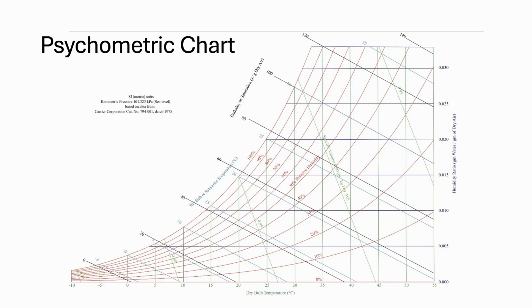So first of all, how much moisture can the air contain, and when is it that the moisture in the air condensates and can become water? So this depends on the temperature of the air. Let's have a look to this chart that you can see in this slide. This is the so-called psychrometric chart. It's a graph that has in the x-axis the dry bulb temperature, so the temperature of the dry air. And on the y-axis, we see the humidity ratio, so the amount of vapor per amount of air that is